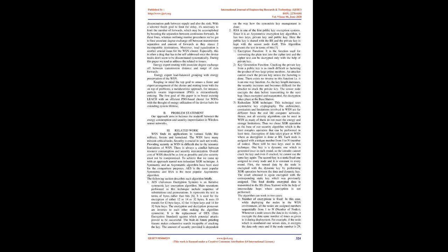Unfortunately, the gateways are likewise battery operated and consequently energy constrained. The lifetime of the gateways is exceptionally important for the long-term operation of the system. The transmission energy, E, connected with distance, D, is based on the following formula, where the exponent is the path loss exponent, Habib and Sujal, 2008. In this manner, reducing the transmission distance will decrease the energy utilization.